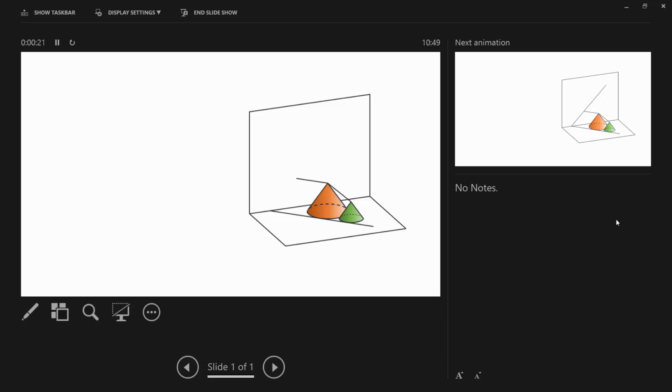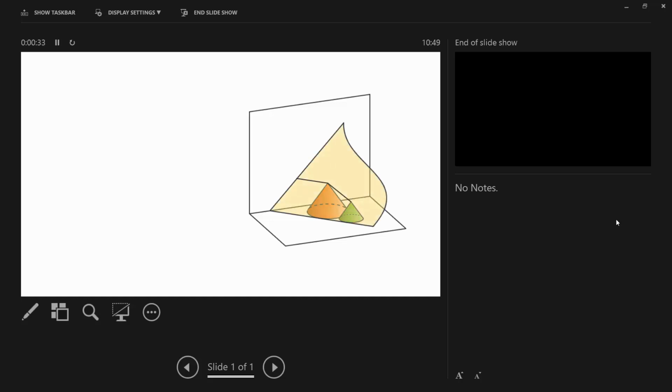You'll see your watermark coming in plan view, going as far as the XY line. Then this little guy comes in. So the two are happening side by side, 2D with the 3D, one being able to explain off the other. There's our VTH, and then click. There's our plane coming in. So that's the process of our 3D with our 2D.